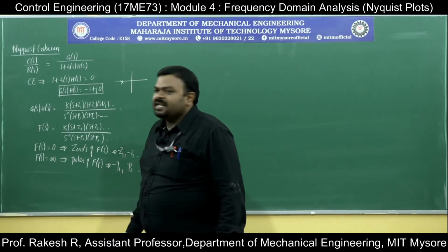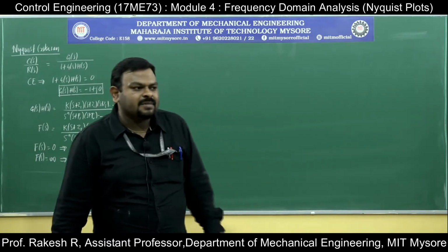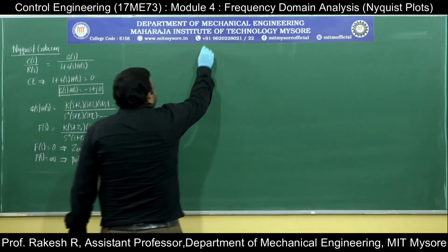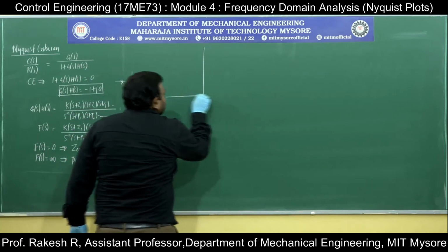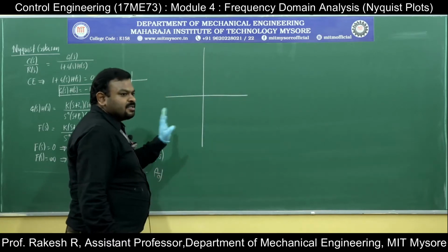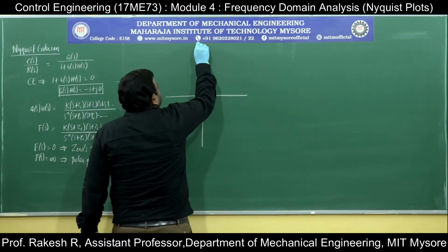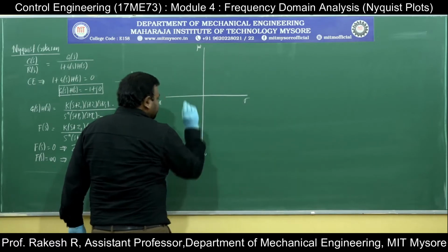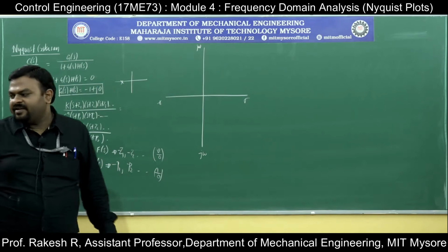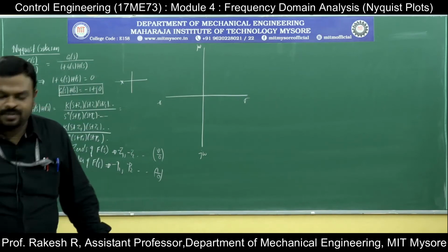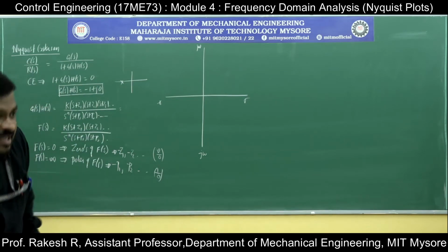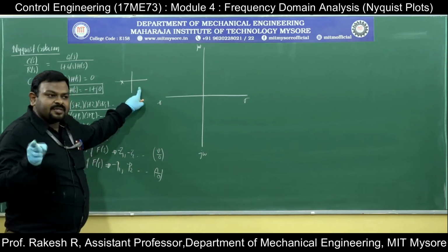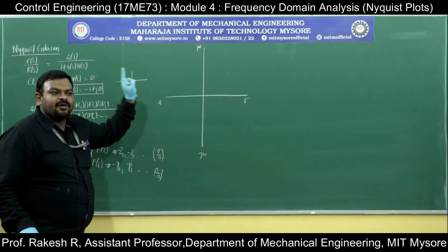After this, Nyquist developed some contours. How he analyzed the contour is, this is one of the contours. So this is the S-plane, with j omega, sigma, and minus j omega. Nyquist has analyzed some of the contours. What he has done basically is, he has calculated whether there are any poles on the right hand side or not.